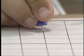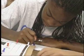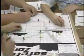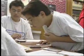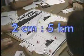Use a pen along with the correct aircraft cutout to mark each starting point. Record flight number, aircraft type, and runway information on the tracking chart. Choose a colored pencil and color each designated aircraft to ensure correct tracking. Now measure and calculate the direct distance in kilometers from the assigned aircraft to the airport using the scale 2 centimeters to 5 kilometers. Record the information on the tracking chart.